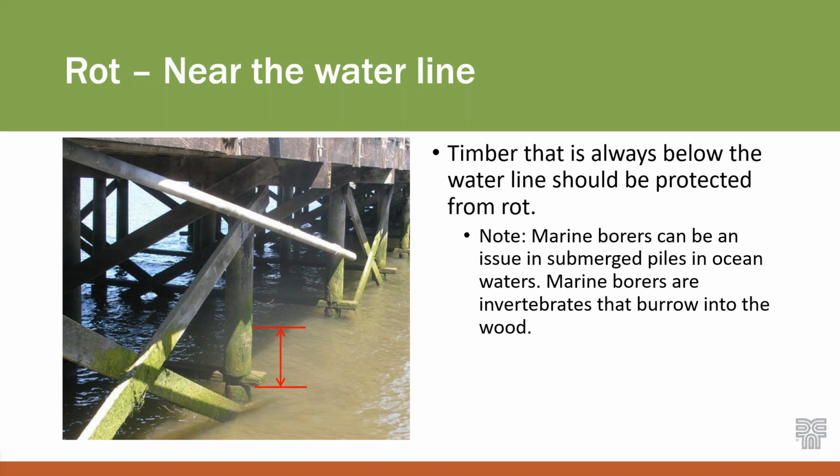One thing I would note is that if you get all the way underwater and it stays underwater all the time, then you've taken away the oxygen component, and the timber piles actually perform quite well. So that's why divers aren't usually finding rot down deep in a stream. What they're finding is towards that water line where you can see it.